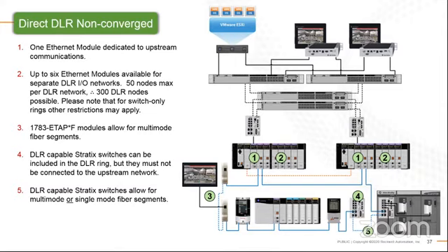Typically, you see the I/O with the redundant power supply. What you'll see here is the main thing that we have is usually a dedicated connection upstream. So this would be communication for the HMI, historian, data analytics, or potentially even from a maintenance point of view, your connection in here. Each Ethernet adapter that you add to the chassis can be in a completely different subnet.